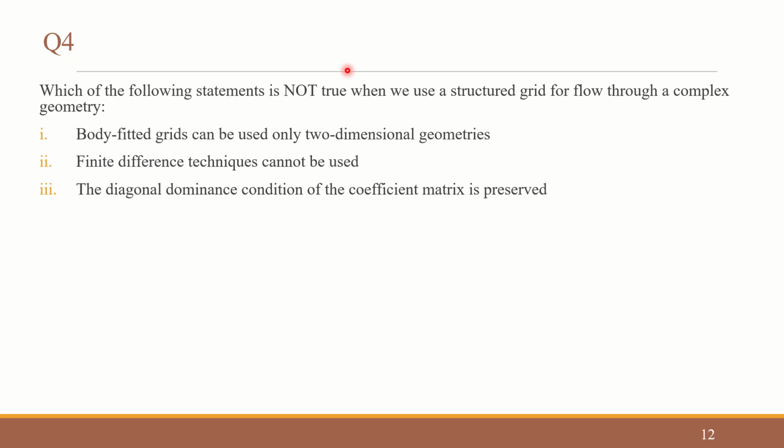And second one is finite difference techniques cannot be used. So that is also a false statement. We can use the finite difference method. In fact, it is much preferred with the structured grid method. For structured grids, using the finite difference method is way easier.